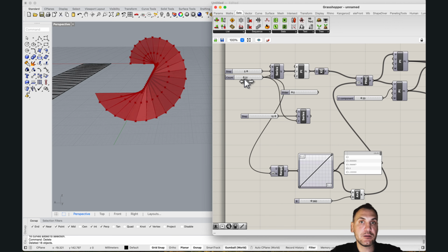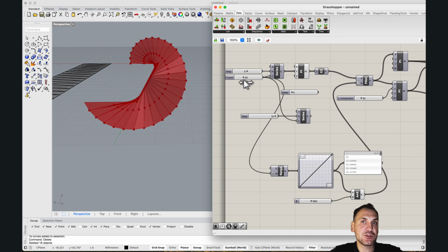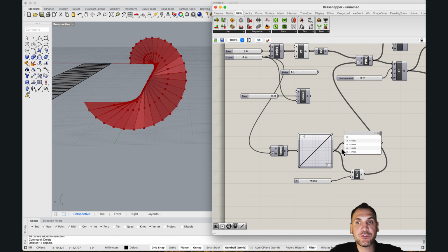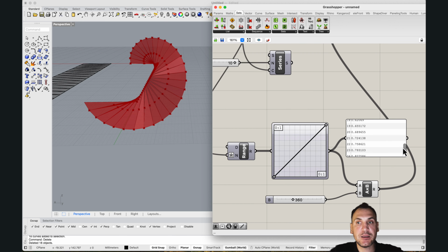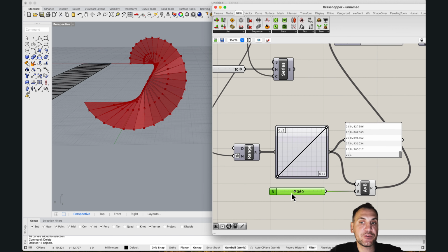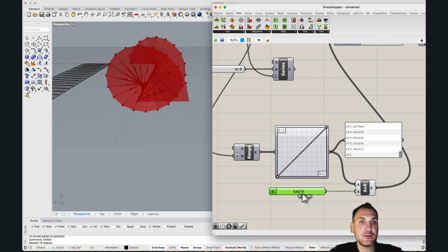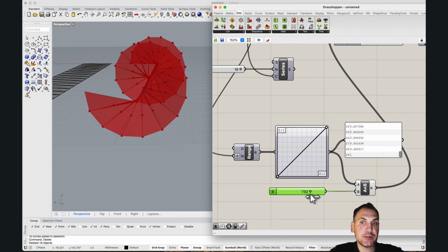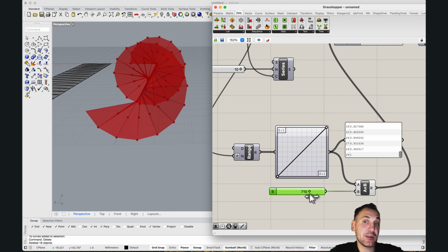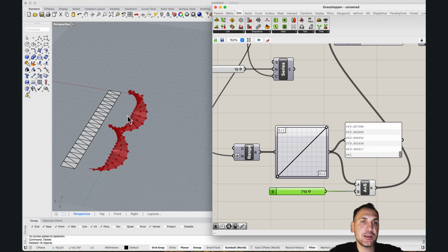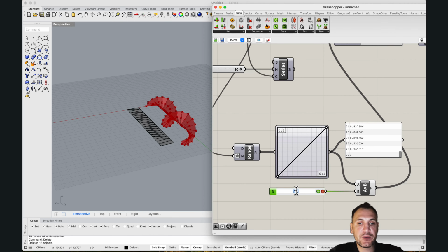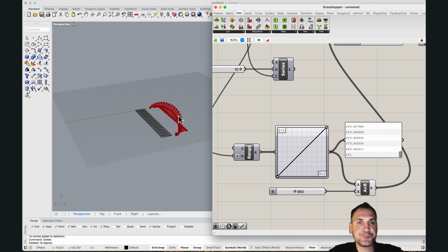But this increment doesn't change the rotation because the range fixes the total number of rotation, right? So we are getting these as coefficients like percentages, and this is the total amount of rotation. I have to change this to be able to rotate it multiple degrees. I would recommend multiples of 90 so that these surfaces can combine later on. But I'm going to keep it at 360.